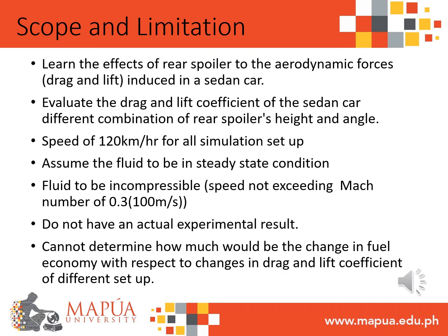Next is to assume the fluid to be in steady state condition. This means that properties such as the pressure, velocity variation, and aerodynamic coefficient will remain the same at any point of time. Another limitation the researchers will set upon this simulation study is making the fluid incompressible, and it can be done by not exceeding a Mach number of 0.3 or 100 meters per second. Since the fluid is incompressible, density variation will be negligible.